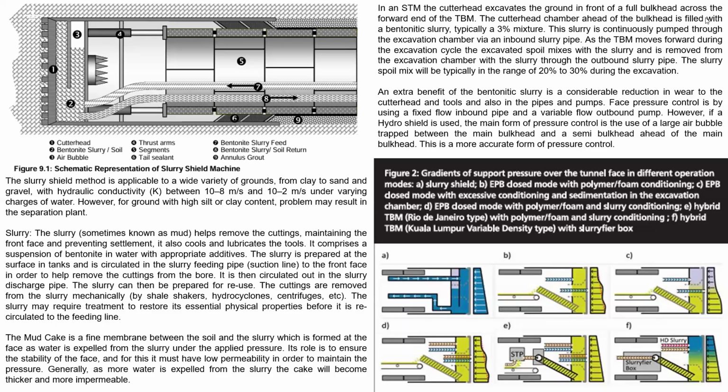There is an air bubble. The air bubble part is mostly very important when there is a TBM intervention, or the TBM is under maintenance, or sometimes there is a replacement of the cutter head and there is no sufficient muck inside the TBM, or not sufficient face pressure we need. So we are applying a minimum air pressure also. But air pressure mostly we apply whenever we are working in the intervention.